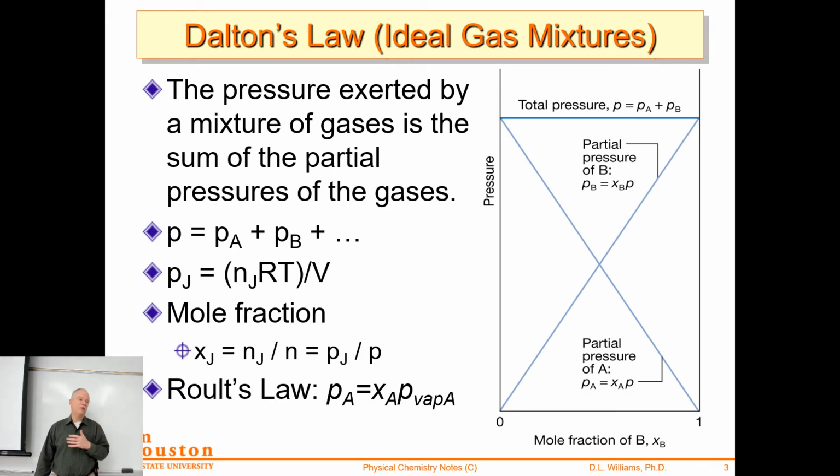So you can look up the vapor pressure for water, you can look up the vapor pressure for CO2, and all of these things would have a vapor pressure at a given temperature. And if you're 50% concentrated, then Raoult's law just says you have 50% of that saturated vapor pressure. So this is a pretty simple linear fit, and those crisscross lines would be Raoult's law.